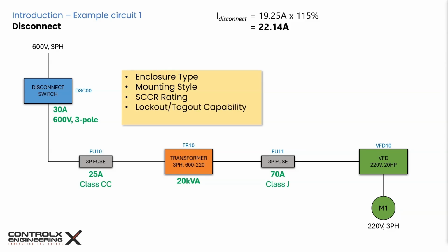Depending on the application, the switch might require lockout tagout, or LOTO, capabilities for safety and maintenance personnel. This is especially critical for industrial applications where personnel need assurance that the circuit is de-energized. The switch should comply with applicable industry standards such as UL or CSA certification to ensure safety and reliability. Confirm compliance with local electrical codes, example NEC or CEC.